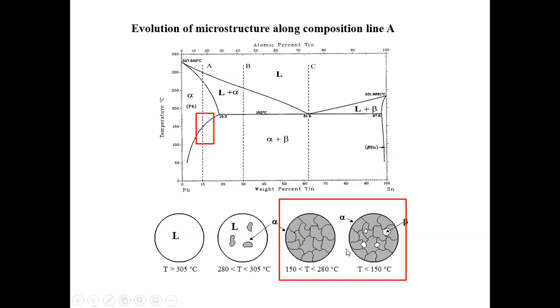Right. In the last lecture and the beginning of this lecture, we spent a lot of time discussing the nucleation mechanisms, comparing the nucleation for this particular solid transformation to the liquid-solid transformation, and we can appreciate the similarities and differences. But we also get some insights, namely that for precipitation growth, heterogeneous nucleation, which means that the secondary phase particles grow on the grain boundary, is much more frequent. It's the key dominant mechanism